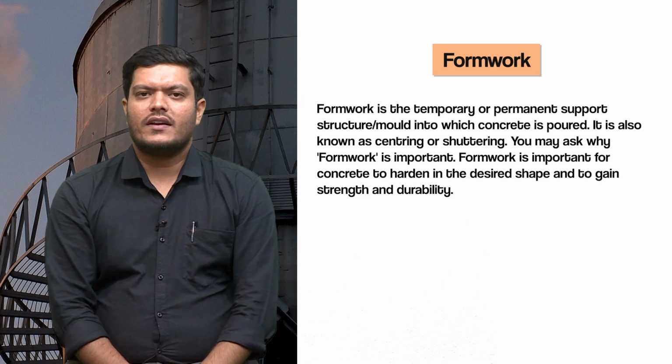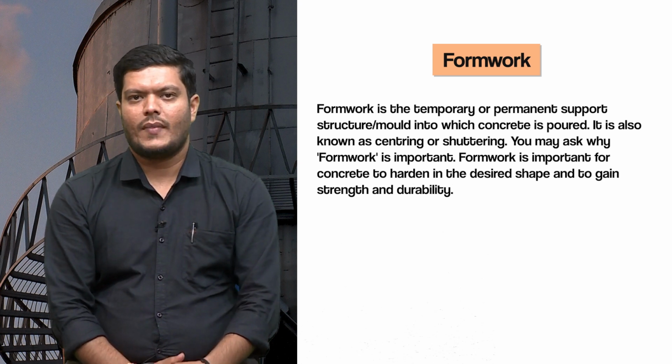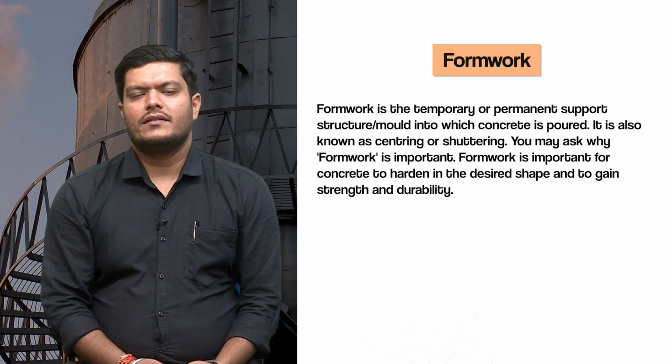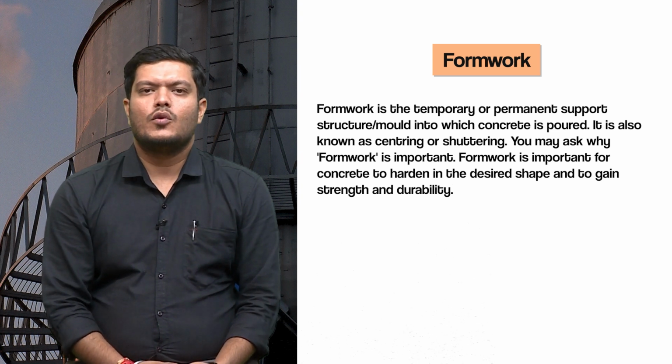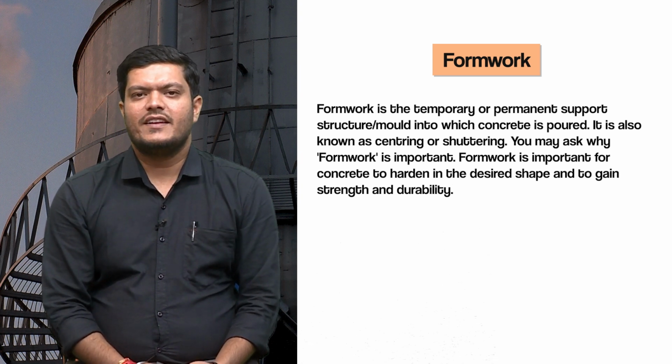Now, formwork is the temporary or permanent support structure, a mold, into which concrete is poured. It is also known as centering or shuttering. You may ask why formwork is important. Formwork is important for concrete to harden in the desired shape and to gain strength and durability.